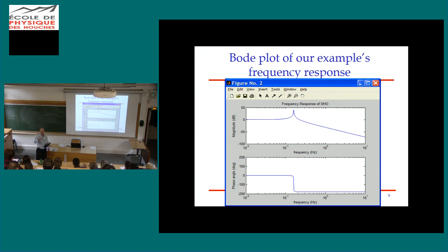It's very easy for me to move the top by a small amount at the resonant frequency. So we know there's a resonance. It takes a little more practice to see that the shoe is lagging my input by 90 degrees, but maybe you can see it. I can move it a lot at high frequencies, and the mass doesn't move. I can't see the antiphase relationship with a shoe, but it's there too. Okay, so you already knew this, or at least most of this, but this is a nice summary.